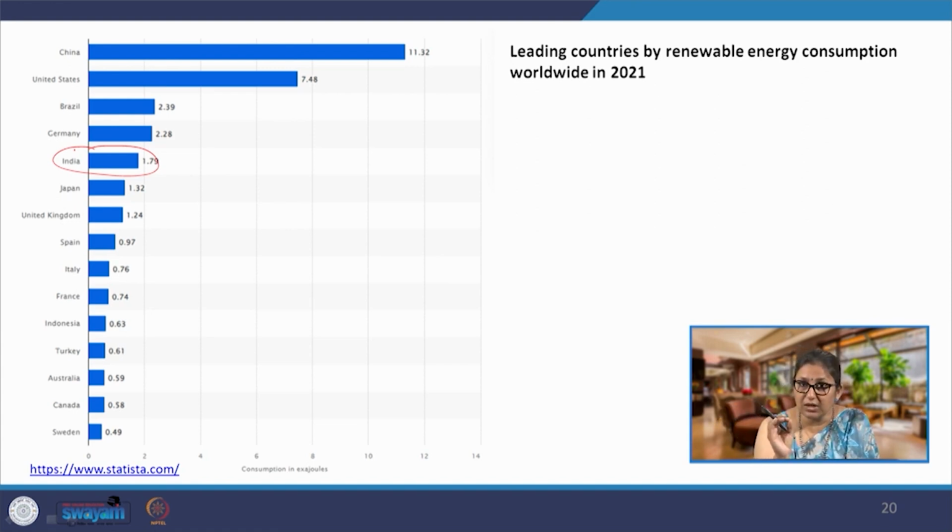So, what we are looking at is, of course, the country is making a shift, but we as building designers and managers have to start generating our own electricity, so much so that each building becomes a net zero energy requiring building. First we reduce the demand, and then we supply the demand by installing the energy producing equipment on our own terraces, and also having a mix. So, multiple sources of renewable energy is what we are talking about.